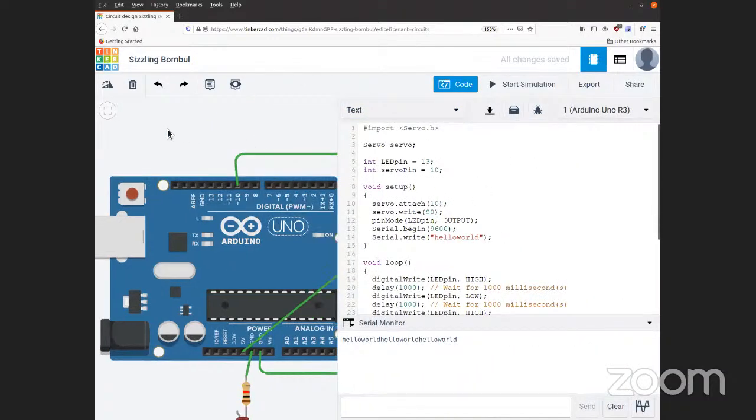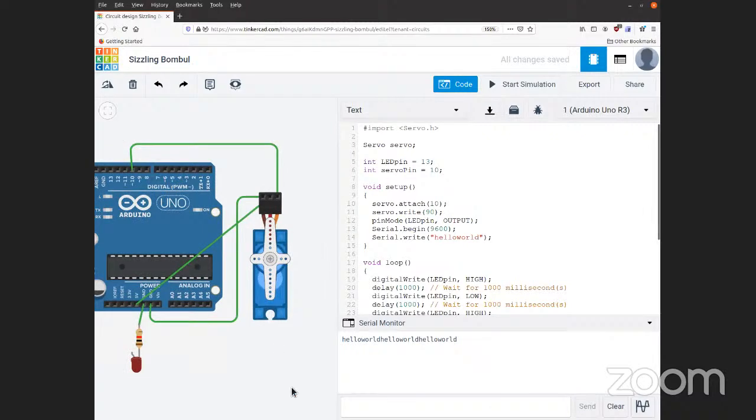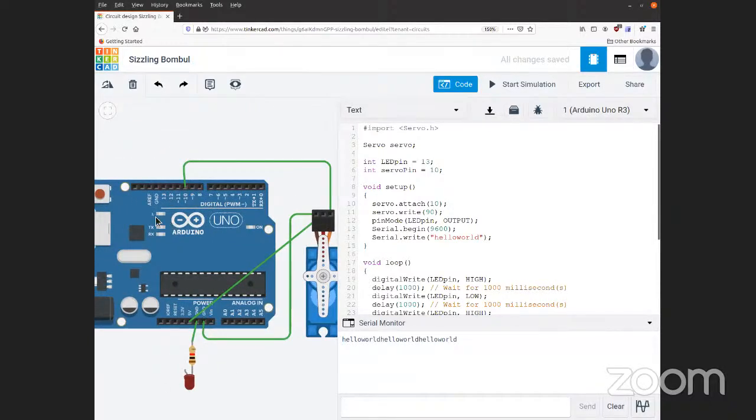There's quite a bit, like that first LED that Michael put on. That was a dumb LED because it was just connected to ground and 5 volts. So the only useful thing that LED could do is tell you the power is on, because when the power to the Arduino is not there, it'll be off. But when the power to the Arduino is there, it's on. There's no software control of that LED. It's a pure hardware LED. Whereas the one that's on the board that's connected to pin 13, that's a smart one. That's one you can control and you can play with.